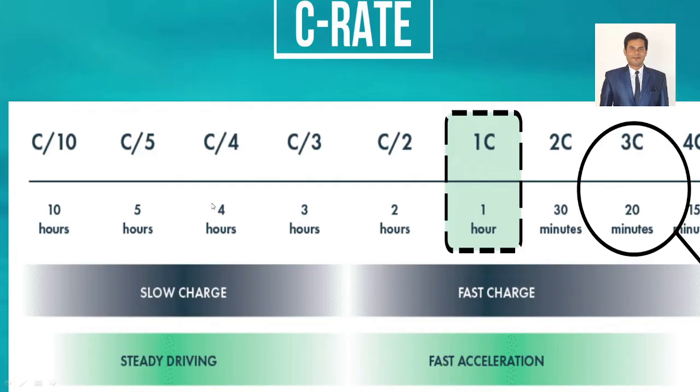During that time, please also focus on the temperature of the batteries, because the temperature has to be maintained very constant, right? It should not increase or decrease. If the nominal temperature is around 25 to 26 degrees centigrade, then please try to maintain that temperature during charging and discharging, right? Temperature should not increase. If the temperature increases, the life of the cells will go very soon. Once the life is gone, you cannot recover it, isn't it?